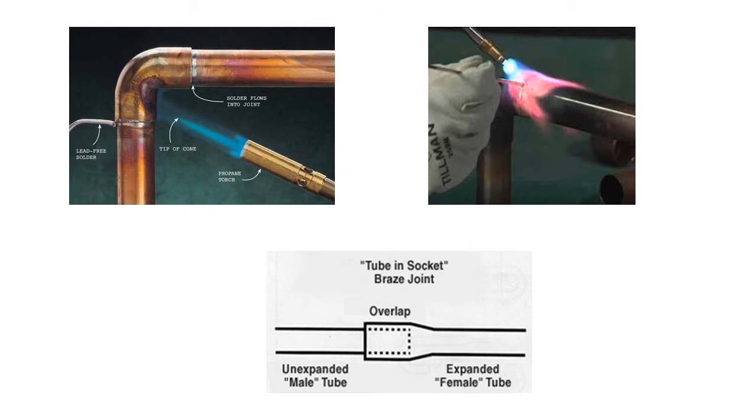Soldered joints depend on capillary action, drawing free-flowing molten solder into the gap between the fitting and the tube. Flux applied to the pipe before soldering acts as a wetting agent and, when properly applied, permits uniform spreading of the molten solder over the surfaces to be joined. What do we mean by capillary action? To put it in very simple terms, it is the ability of a liquid to rise into a narrow gap or passage against the force of gravity.